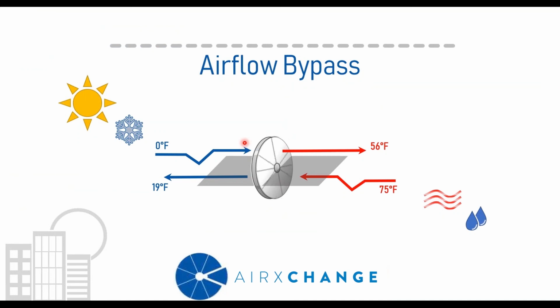Okay, the third method that we're going to discuss is airflow bypass. Airflow bypass works on a similar principle as wheel speed control, where you're trying to minimize the wheel's ability to transfer heat and humidity. By bypassing a portion of air around the wheel, you're essentially minimizing the pool of energy that you can use to treat the air.